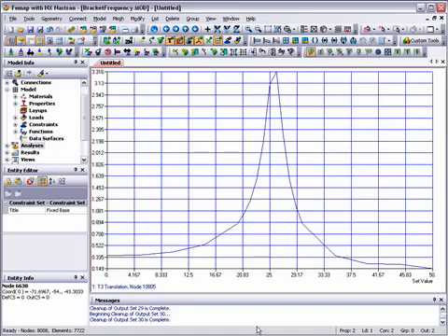Therefore, with the requirement to maintain a deflection of less than 1 mm at the motor center of gravity node, any dynamic base excitation loading with a frequency between 20 Hz and 30 Hz would require a redesign of the bracket. This shows that in many cases, a simple static analysis review is not enough. Femap with NX-Nastran can take the analysis further and model a more realistic representation of the design and its working environment to give more accurate and complete answers.